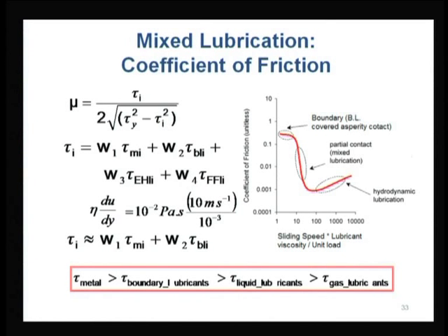Of course, if we talk only about fluid film lubrication, in that case we need to account for this, even the lowest coefficient of friction we need to estimate through that, or with EHL we need to estimate coefficient of friction, but that will not be relative, that will be in an absolute sense.